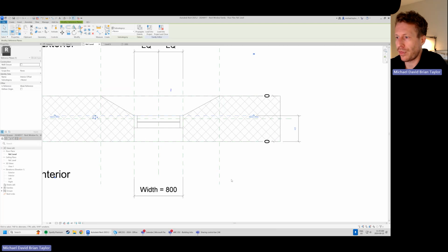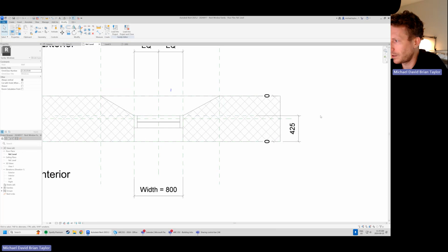But you can see again how thick our wall is. This is really one of the challenges of these really deep wall assemblies. We want to situate that frame in a place that makes sense. So why don't we just go ahead and make sure we lock this. You're going to click on the dimension and click that little lock. Save our model. So save it.